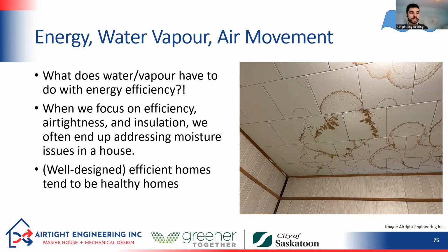This is a picture of a room that I stayed in, in a community in northern Ontario, and we see some moisture issues happening here. This is actually not leakage from the roof. It's not from rain. This is because there's not enough insulation in the ceiling. And so when someone's sleeping in the bed below, they're breathing, they're creating humidity, and those ceiling tiles are too cold.